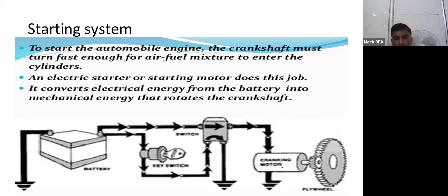To start the automobile engine, the crankshaft must turn fast enough for the air-fuel mixture to enter into the cylinder. So that is the cranking. Already you know how many strokes are there: suction, compression, expansion, and exhaust. So an electric starting motor is used to start the engine.